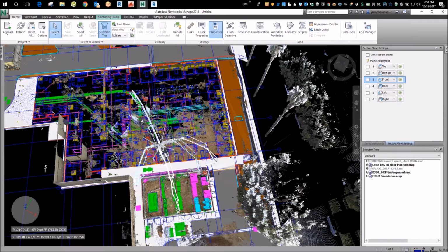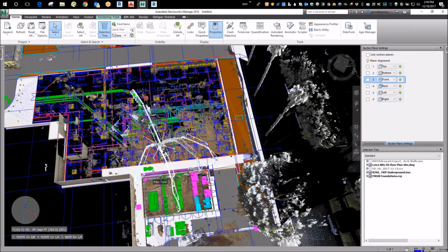So we have to ask Ryan, next time your surveyor comes, make him give you control and the coordinate data that goes with it inside, so we can set up somewhere in there and sync up in the building and start to shoot stuff. Outside's a little easier where you have more straight line of sight, but clearly it can be done.